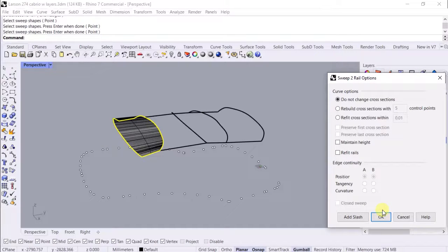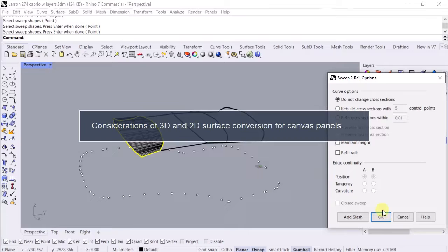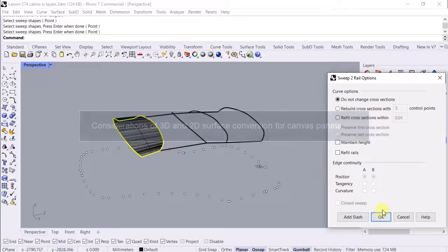Before continuing, we will address an important aspect of working with 3D canvas in CAD. The end goal of any canvas project in CAD is to cut two-dimensional canvas panels that can be sewn together to form a 3D structure. With PhotoModeler and the first parts of the CAD work, the process is in 3 dimensions. To generate 2D shapes from 3D surfaces, we must flatten 3D surfaces. In addition, you want to flatten your surfaces so there's minimal distortion or fabric stress. This can be done from 3D meshes using an extra plugin, but we do not address that here.